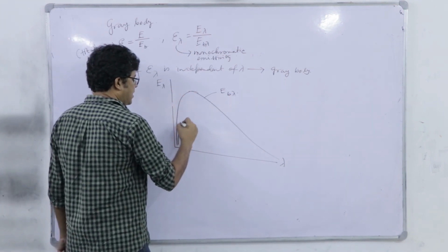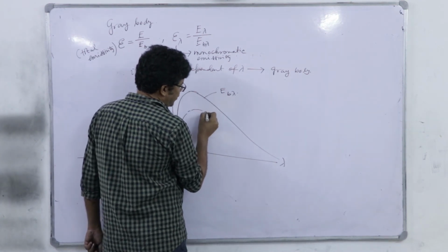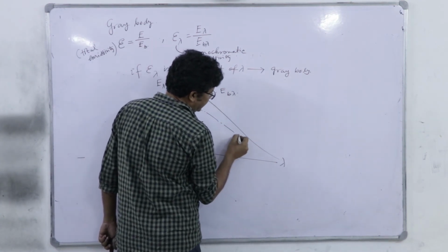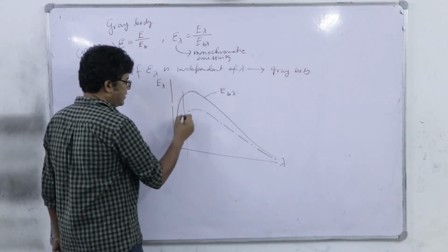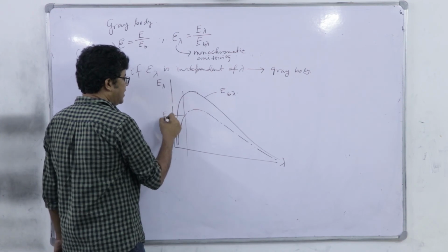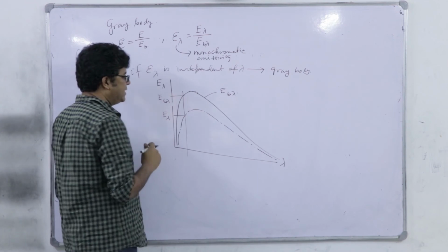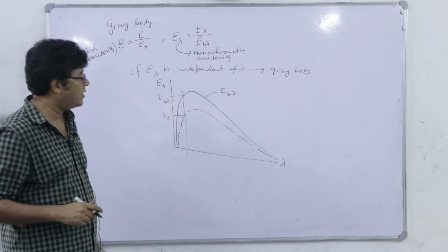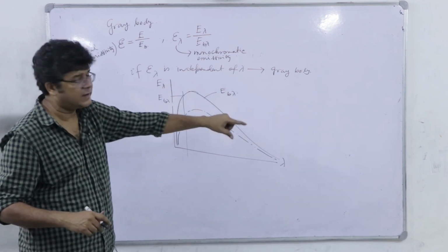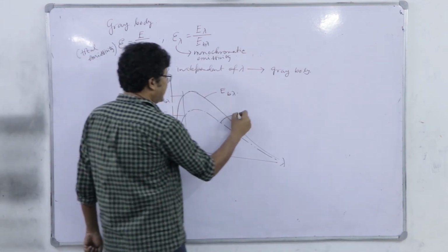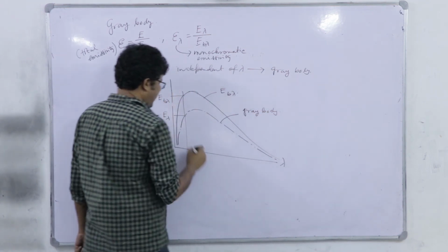And if I think of another curve which is proportionally changing such that at each and every point the ratio remains the same, like here this is E lambda, this is EB lambda, or for any other point the ratio of E lambda and EB lambda remains the same. So, this is a scaled down version of this black body's curve. So, this is gray body, right.